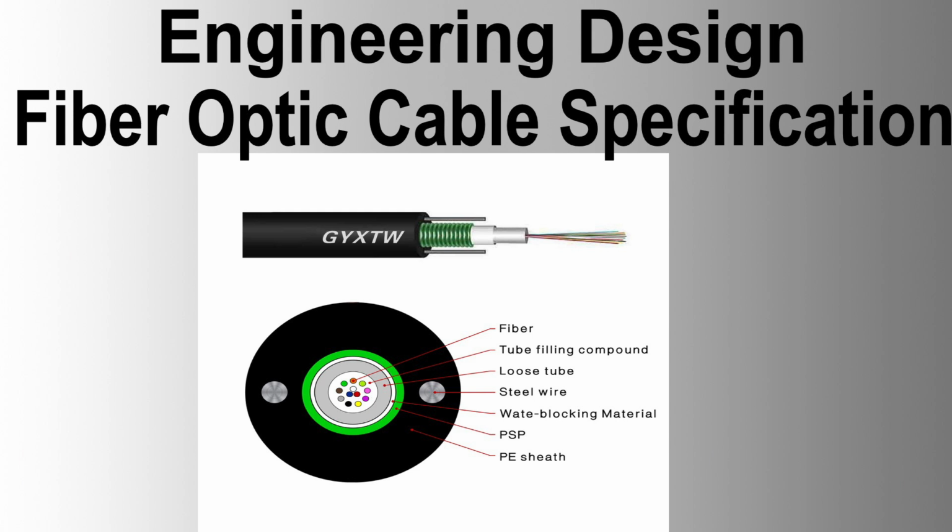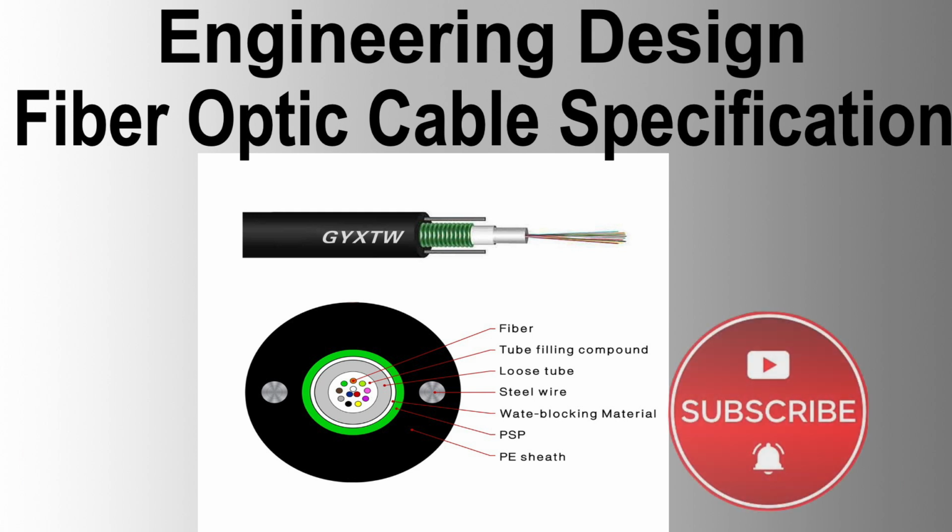Fiber optic cable tests. The contractor shall develop complete procedures for the splicing tests, fiber optic tests, etc. Each fiber optic cable shall be tested for integrity, and a test report shall be issued, providing figures of fiber attenuation and remaining fiber optic budget margin. This report shall be signed off by the contractor and company.